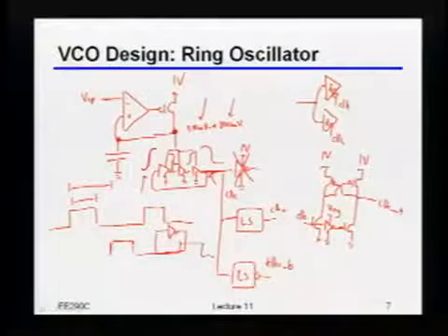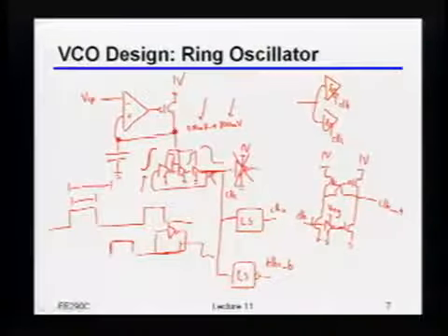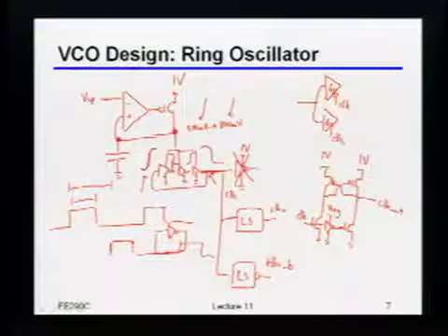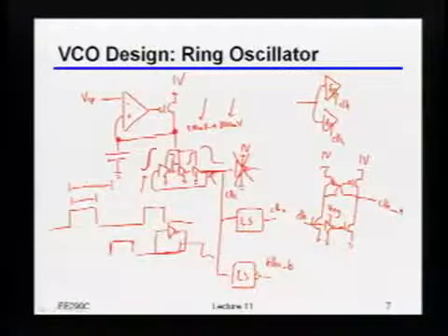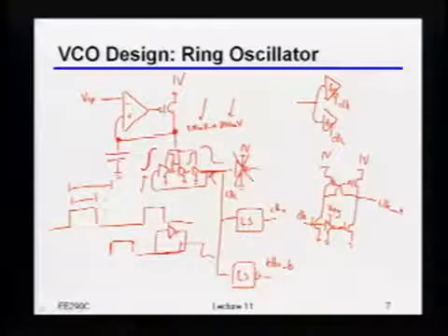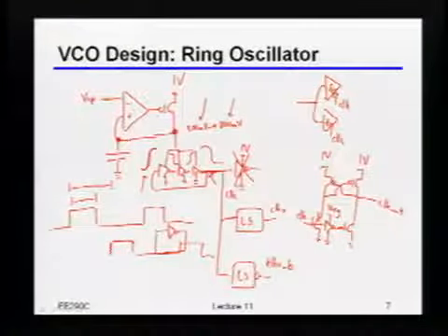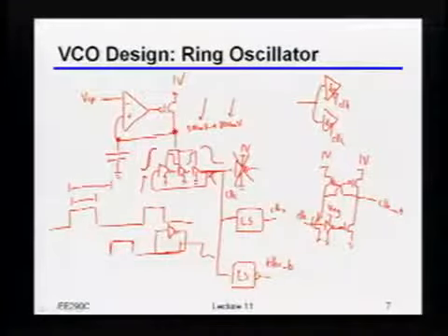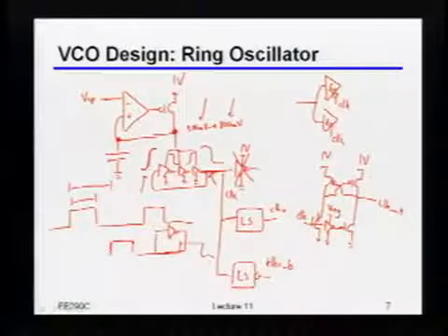And inside, if it's a 3-stage, where did you get the clock bar? Because there's no 180-degree phase. That's right. So that's what I'm saying, I won't really get clock bar. I'll get clock bar plus 60 degrees or whatever it is. Right, and then when you choose two parts, how do you get the clock and the clock bar from the beginning? Oh, okay. So if I really did it, then I would probably just phase split or something like that. Then that phase splitting depends on the supply voltage, right? Yeah, that's right. So by the way, there is no perfect way to do it.